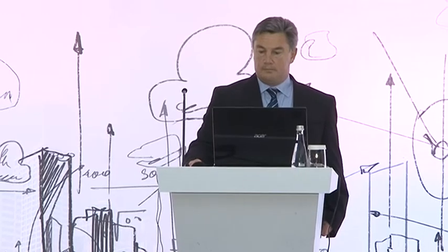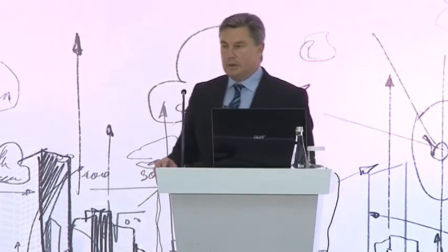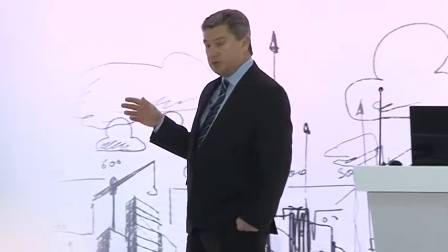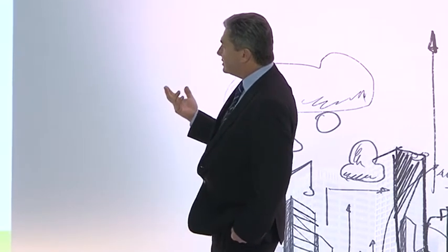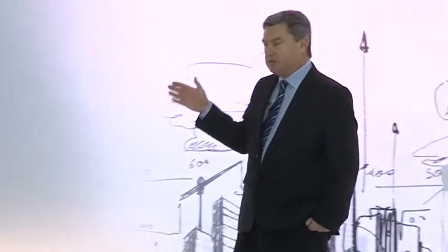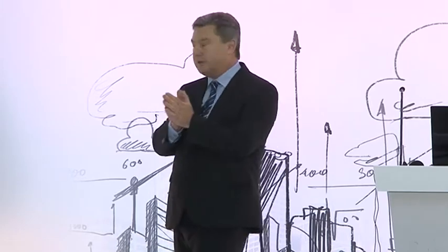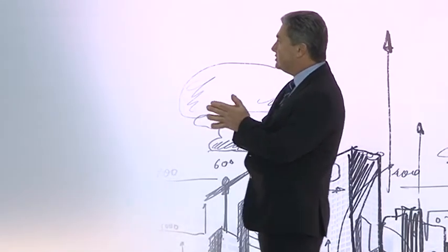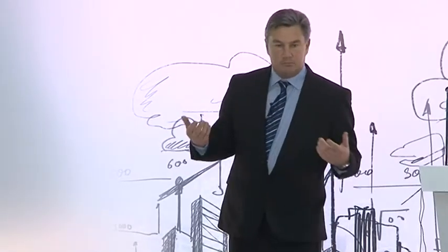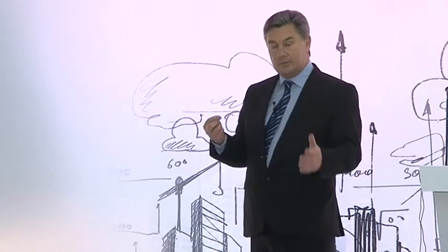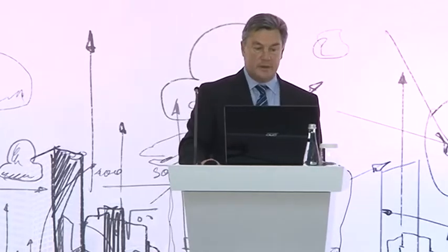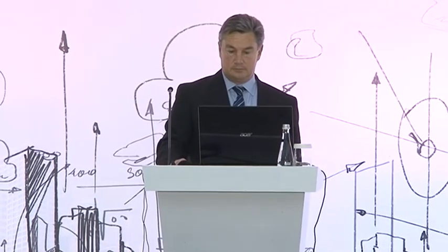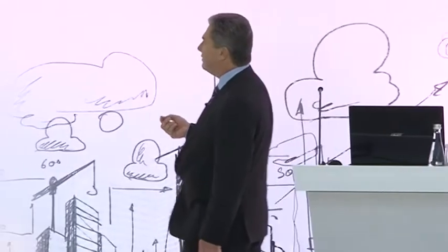Okay, we can also put on period figures, which is useful. So this is like putting this into, in this case, monthly chunks. So this is telling me how much duration I've got built into the plan in a particular period, which is very useful if I've worked out for health and safety how many toilets I need on the site at a particular time. I can see whether that's going according to the plan. Or if I'm looking at a resource-based curve, the numbers of people I'm expecting on site.